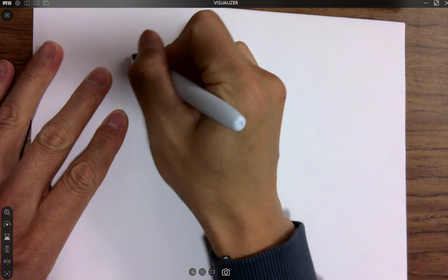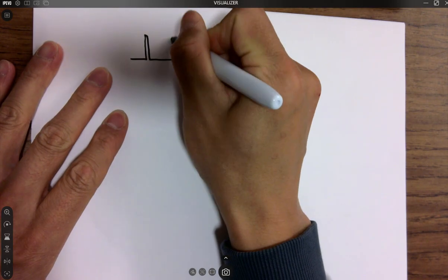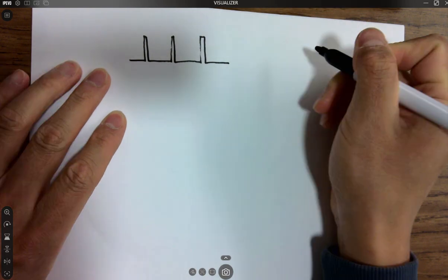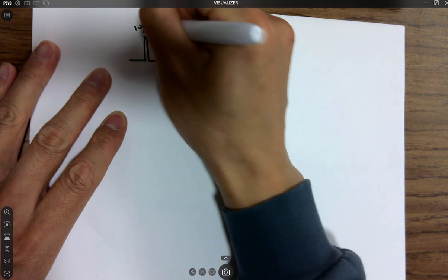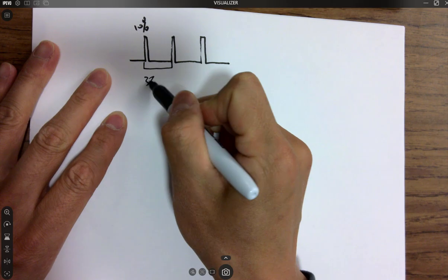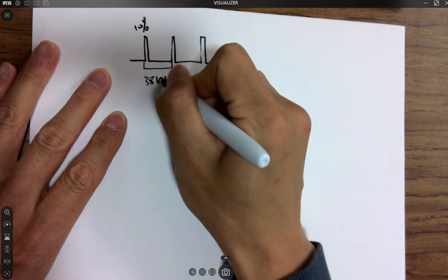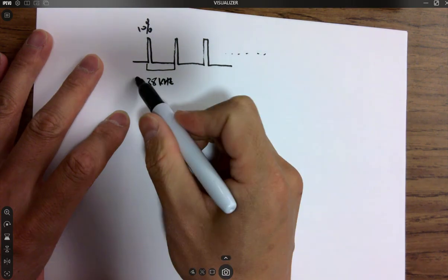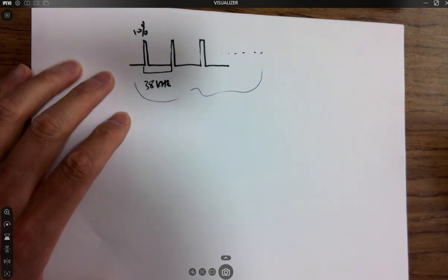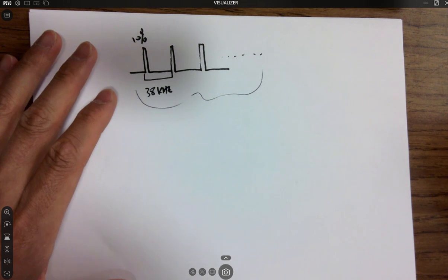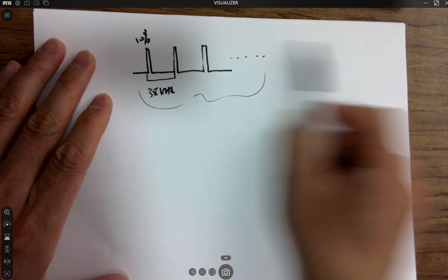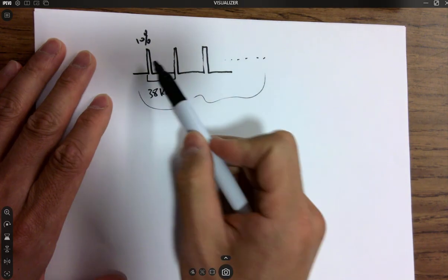It actually doesn't matter. So the IR is like this. Remember what's the duty cycle we are using for this example? It's 10%. And here's the frequency, 38 kHz. Okay, so there will be a lot of these pulses, but how many are required to make it happen? Doesn't really matter, as long as you have, I don't know, more than 10 or something,